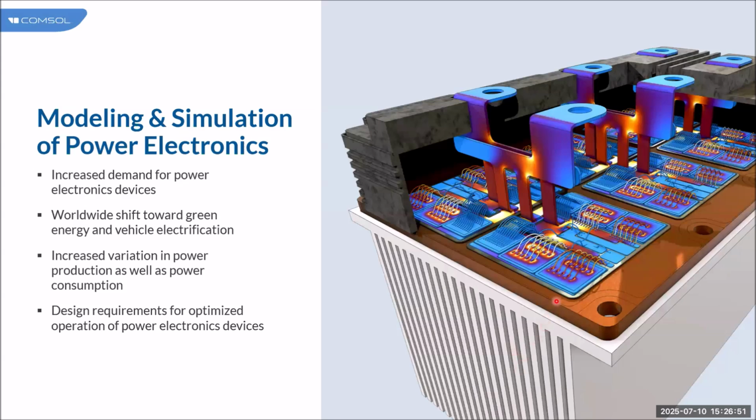Another strategy we adopt is that in COMSOL we have an electric circuit module, which is part of the AC/DC module, where we can connect the particular excitations as well as lumped models of resistor, inductor, and capacitor, and some of the active switches, whether it's a BJT or a MOSFET. All those things are available as lumped models, which can be directly connected to the FEM model, making a co-simulation approach. The electric circuit is an analytical model, coupled with the finite element method, which is a numerical model, I would say. So this also is possible in the power electronics approach.